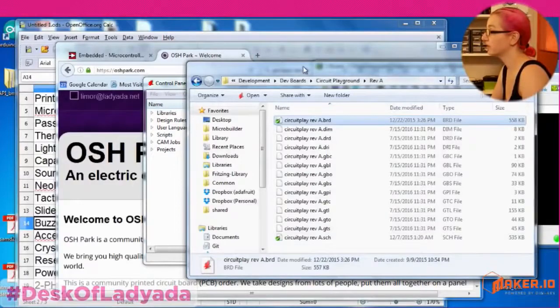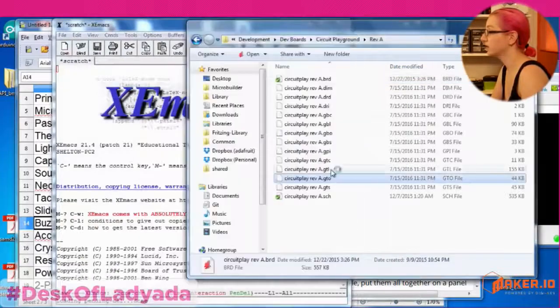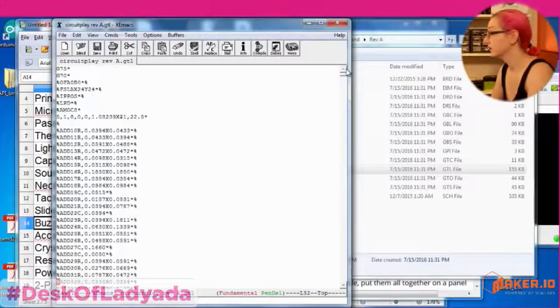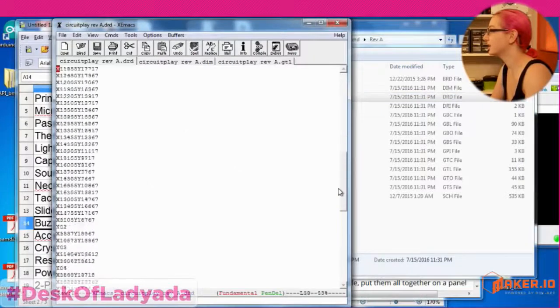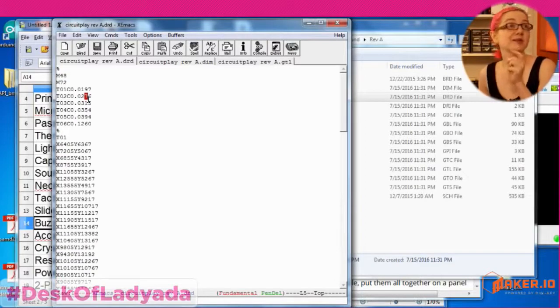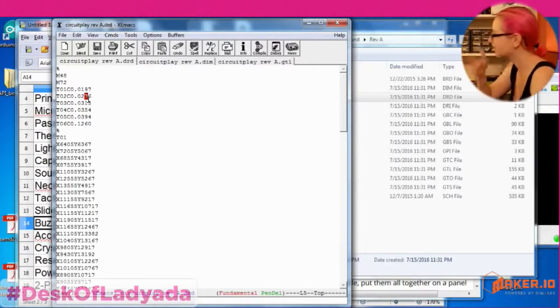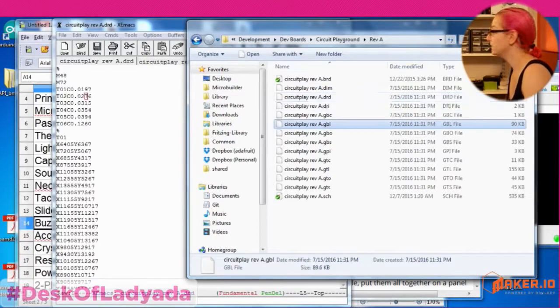So these are the Gerber files that got generated. Gerber files are just text files. You can actually open them up and look at them. It's just a description. Sometimes, for example with drill files, you can go in and edit drills, and I have done that. Rather than going through and editing all of the vias, I'll go in and tweak the drill file. It's not recommended, but you can do it. I've done it. And all of these drill files and Gerber files, you can view with a Gerber viewer.